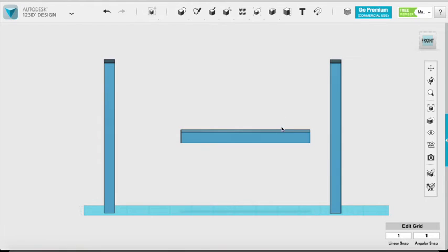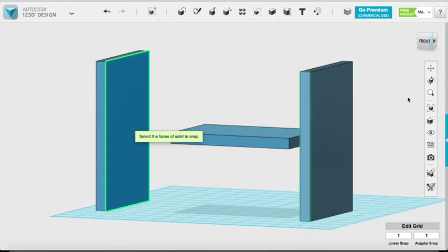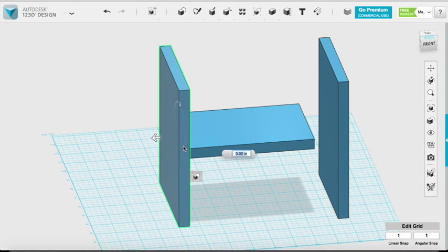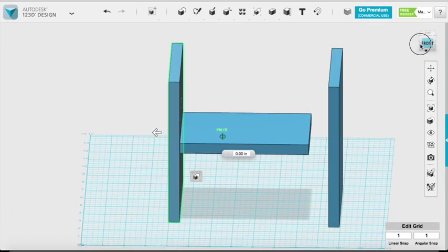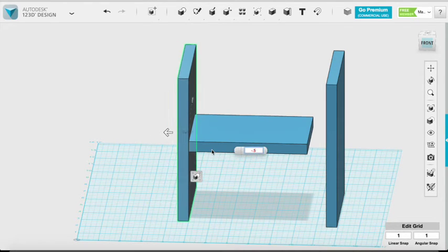I'm going to hit OK, and you're going to say, but they're not touching, which is true, which is what I'm going to do with my snap tool now. So I'm just going to snap this guy to the end of my board itself. But notice it's sitting right on that edge, but it's not inside of it. In order to make this perfect, I think I'm going to have it go negative 0.5 so that this end slides into the board ever so slightly.